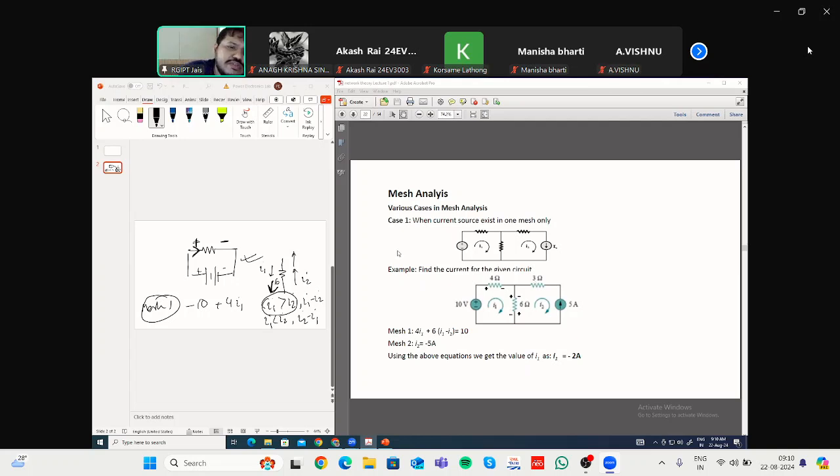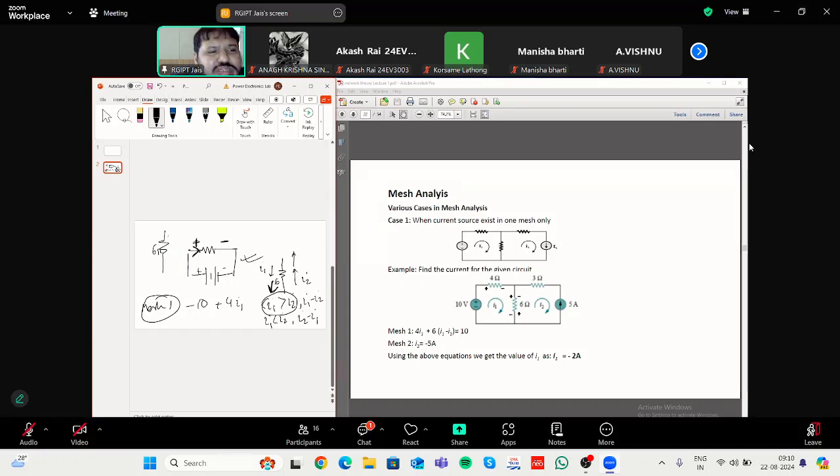Yes. If you don't take it, then what is the solution? Because you have to assign this plus and minus sign, you have to know in which direction the current is entering. Let us say this is the 6 ohm resistance. You don't know whether to give the plus sign here and minus sign here, or plus sign here and minus sign here. How can you know? By knowing the direction of the current. I have already told you, if the current is entering from a particular side, that will be at higher potential or positive, and the other side will be negative. So to know which side is positive and which is negative, you have to know the direction of the current.